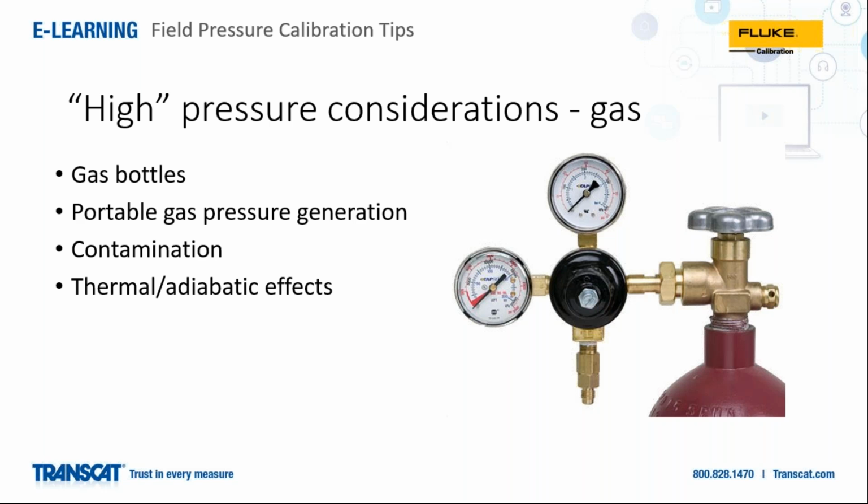So as you're decreasing pressure from the device under test, do you have a potential of pulling back liquid or particulate stuff out of the external system into your standard? And another consideration is thermal or so-called adiabatic effects related to temperature. So as temperatures fluctuate, pressure fluctuates as well.